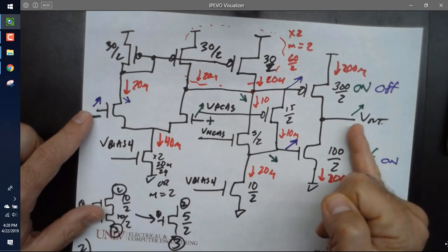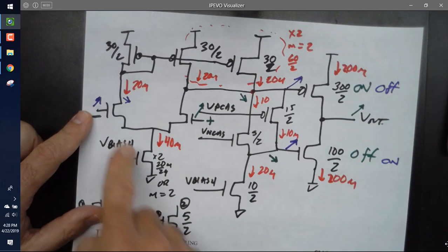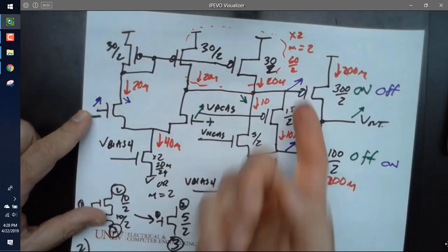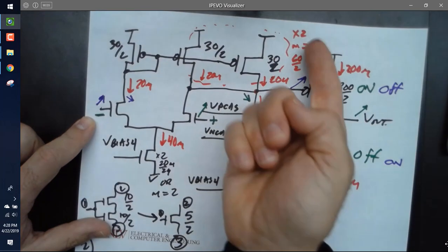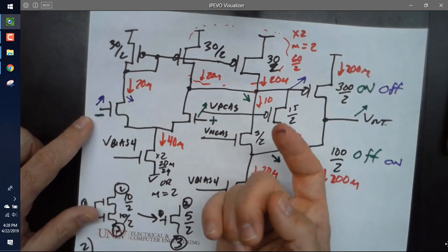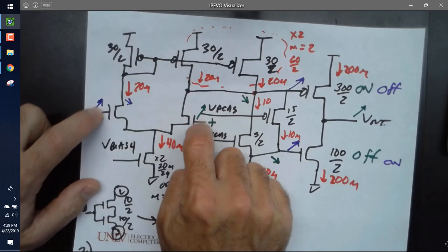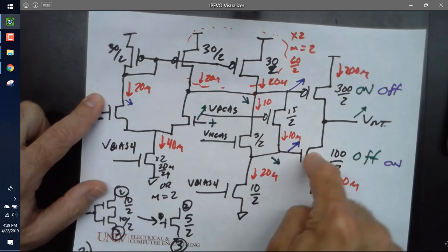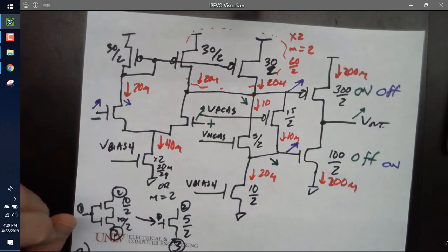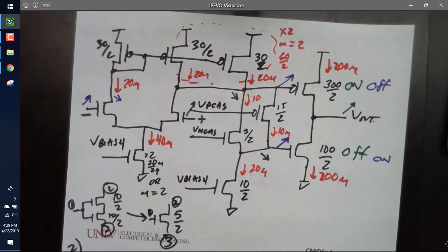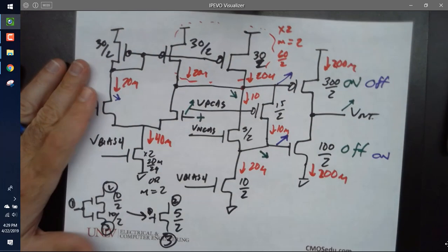But what happens if you put a resistive load here? The gain's going to go down, but also I got to supply the current from this one. So what you might do in your design, hint, hint, is size this up so it supplies more current and you get what is called an offset. In other words, these have to be a little bit off in order to make this current equal this current, because you size this one up because it's got to drive a resistive load. An offset hopefully, if you have high enough gain, is only a millivolt or something. All right, there's trade-offs in real op amps. Now, I'm going to go through this part of the circuit in a couple steps.